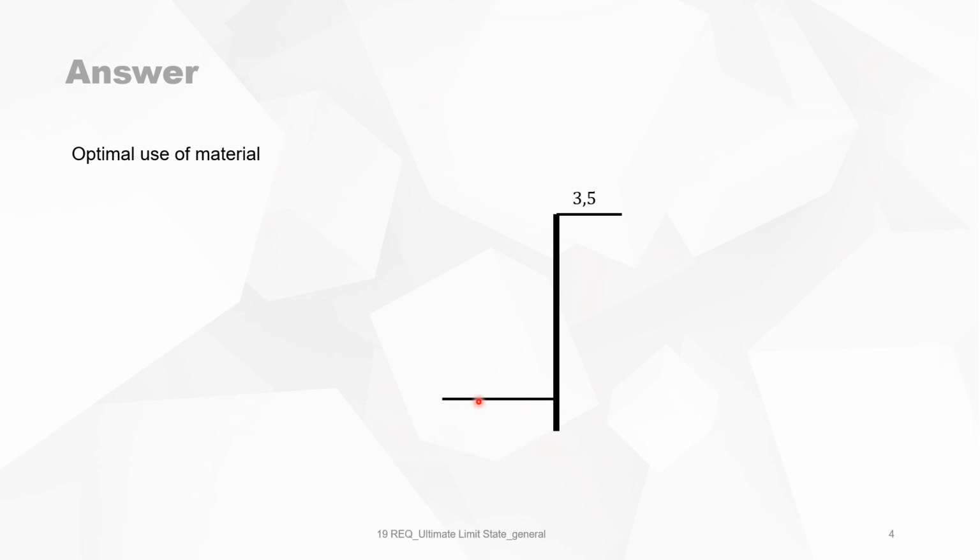The point of gravity of the tensile reinforcement is situated here, and this is the maximum strain in the reinforcement, which is 10 per mil.